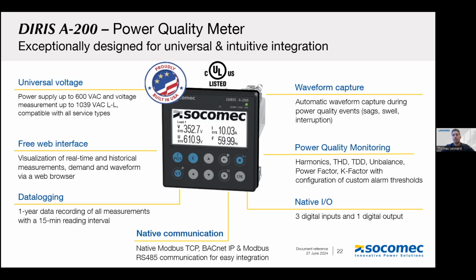The A200 also has some native input-outputs, 3 digital inputs and 1 digital output, which we'll talk about a little later. And for power quality events such as sags, swells, interruptions that we talked about, the A200 will initiate an automatic waveform capture during the event. So it'll capture the event, it'll store the waveform, and on the web interface, you're able to visualize the waveform during the event. So that's something that can be used as proof to the utility, when you have a summary of active and past alarms with details such as duration, amplitude, and the waveform capture. That really serves as proof when you're going back to the power provider.